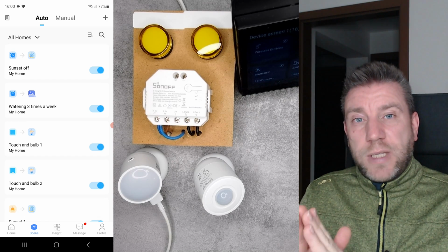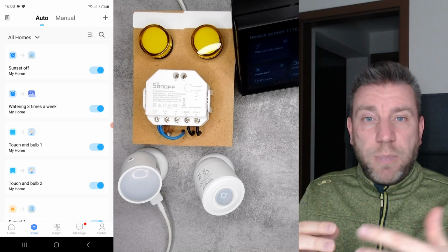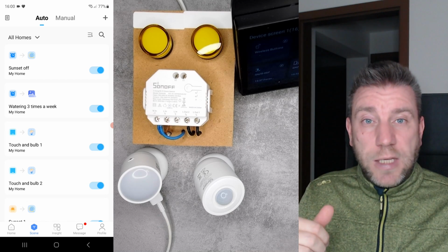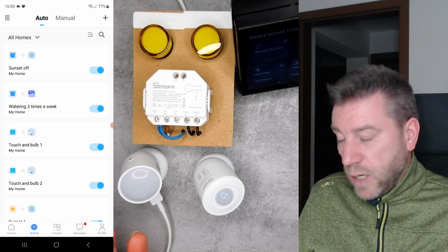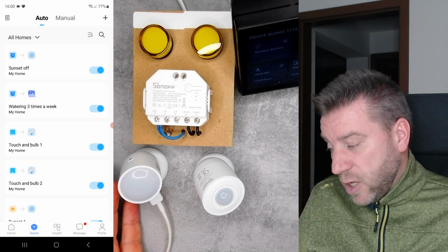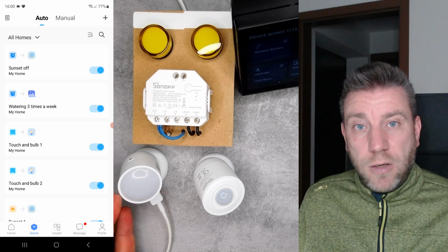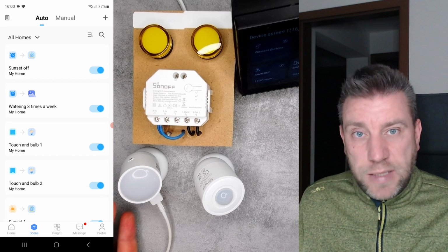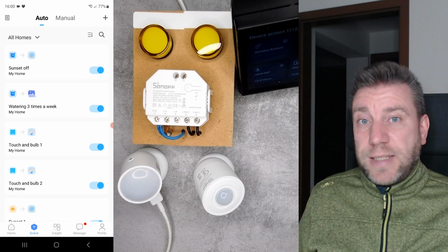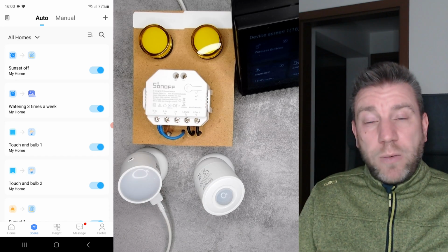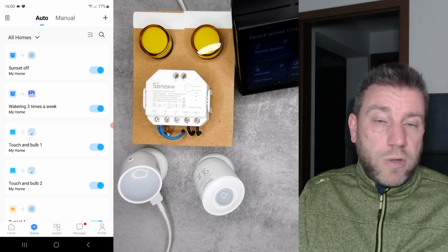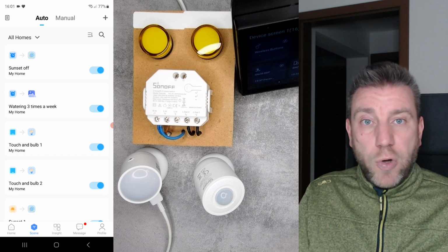So when the window sensor breaks the connection, it basically just turns the AC off. So that's something that we can use with, let's say, a presence sensor. If it doesn't detect any presence in the room, we just send the signal to this mini split, the same signal it would receive if the window gets open. So it basically just disables the heating or cooling.